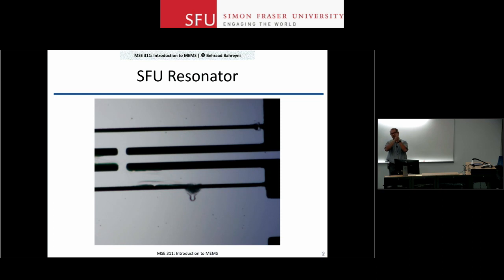The situation here is that the two contacted. This device was operating at hundreds of kilohertz, so the video could not capture it. But the two contacted. Once the two electrodes touched each other, you basically melt silicon at that point. You have a high voltage applied to this device, let's say 10 volts, 20 volts, whatever, and you have a tiny contact point, a lot of current goes through that contact point, and you melt the device right there.